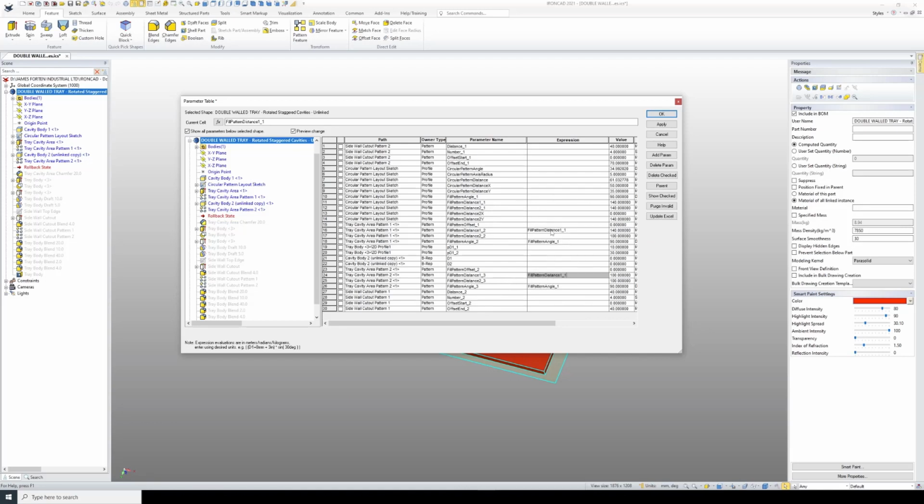And so what I'm telling IronCAD is that I want the values from these parameters here to populate these parameters here. And then the next one was fill pattern distance 2, and this is going here and here. So what I've done is I've created links now where the fill patterns are going to follow the parameters of the sketch.